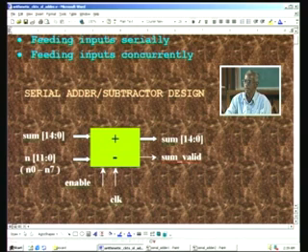This is clearly arising on account of the fact that we have 2 to the power of 3 number of inputs. That's the reason why 3 bits extra are coming here, and when this sum is valid is indicated by another binary signal here, and all this transaction will take place only when enabled, that is when enable is high.